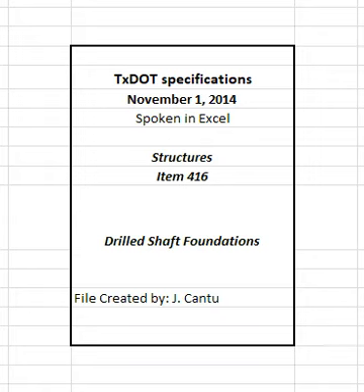Do not attempt to remove this concrete with shovels, pumps, or other means. Level the top of shaft with hand tools as necessary. Use a sump or other approved method to channel displaced fluid and concrete away from the shaft excavation. Recover slurry and dispose of it as approved. Do not discharge displaced fluids into or near streams or other bodies of water.